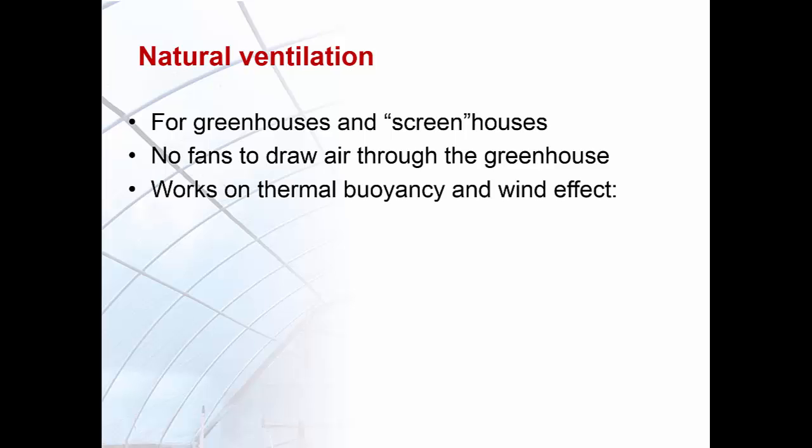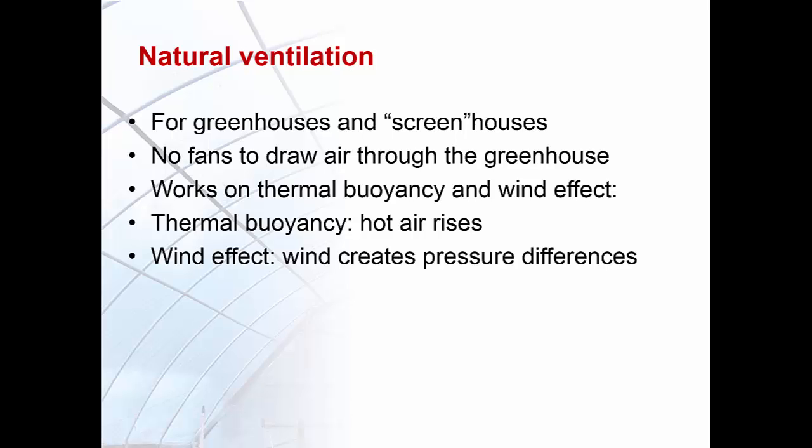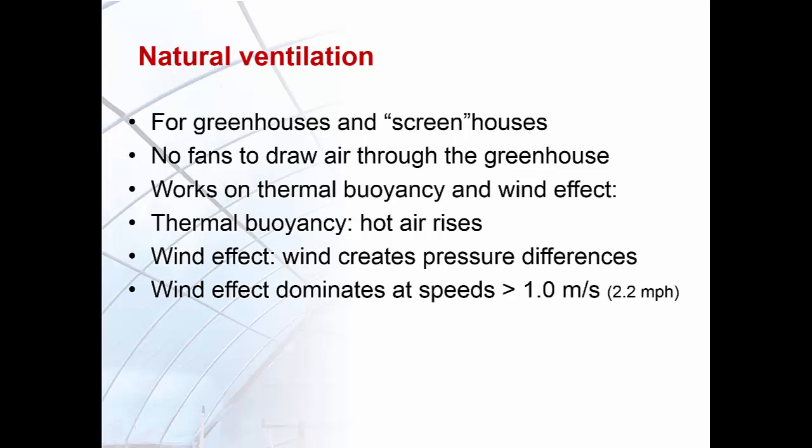Natural ventilation works on thermal buoyancy and wind effect. Thermal buoyancy helps hot air to rise because of reduced air density. Wind effect creates pressure differences contributing to natural ventilation. Wind effects usually dominate at wind speeds higher than 1 meter per second.